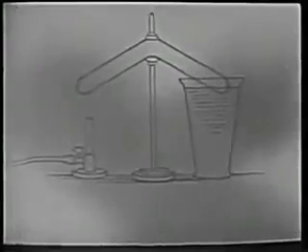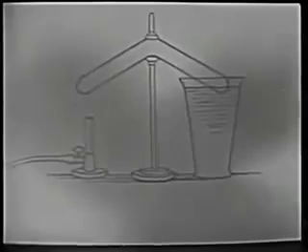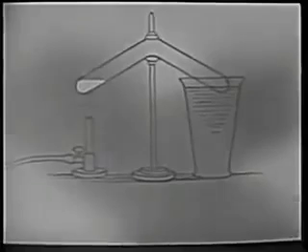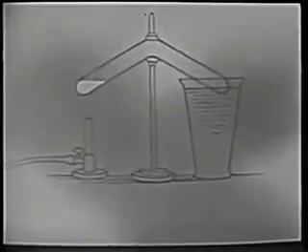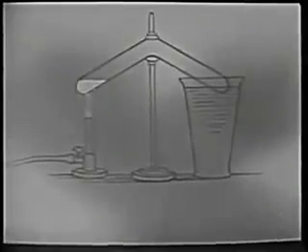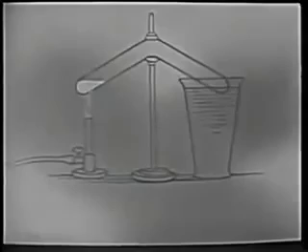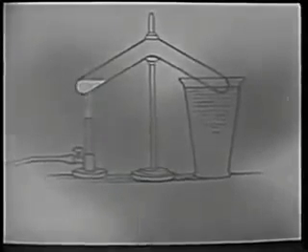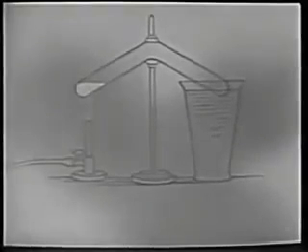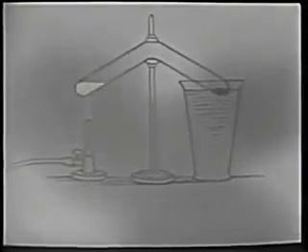The absorption system is based on principles developed in a famous experiment conducted by Michael Faraday. He sealed in a bent test tube a compound of silver chloride, a white powder, and dry ammonia gas which had been absorbed by the powder. He heated the end of the tube containing the powder and at the same time cooled the opposite end of the tube with water. Ammonia vapor was released during application of heat and was condensed in the cool end of the tube. When the flame under the powder was extinguished,